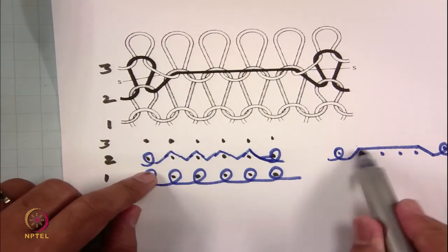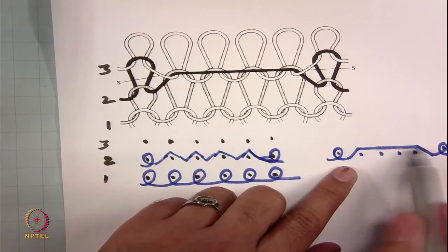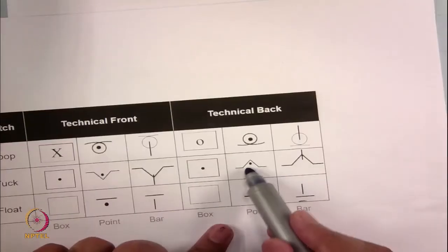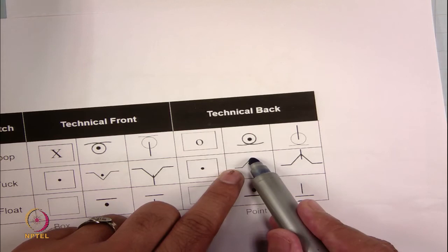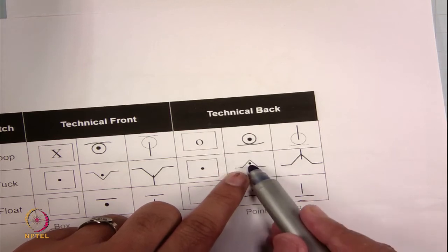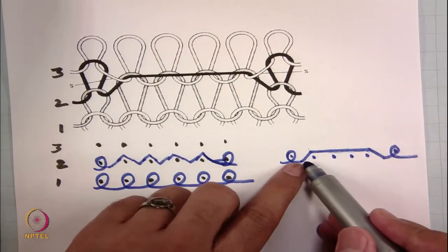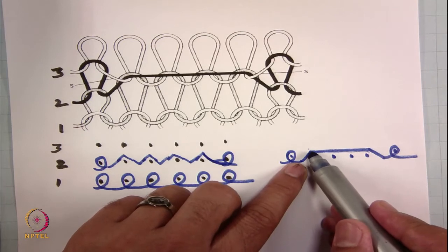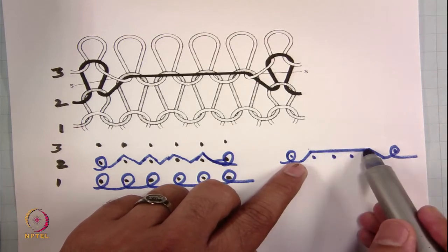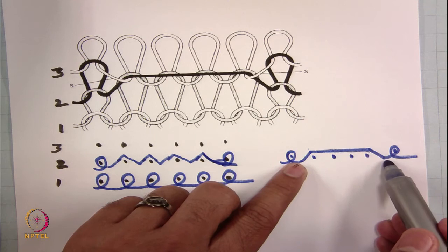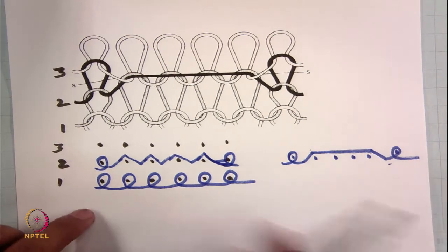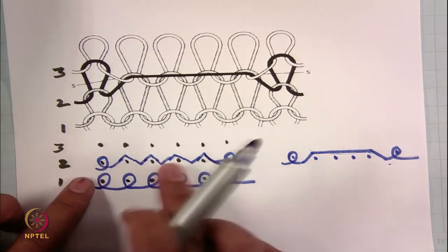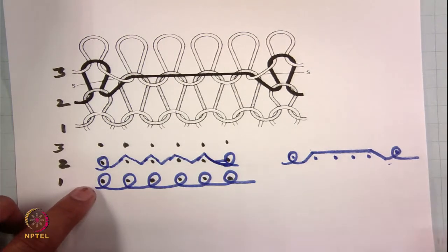That is why they become straight. This is again the tuck position. If you carefully see, the yarn is going from one side and then it is moving towards the other side of the needle. Here also from one side it is moving towards the other side of the needle and consecutively it is making 4 tucks and then it is going back on the other side to make a technical back loop. So, either you represent the second course this way or this way, it remains similar.